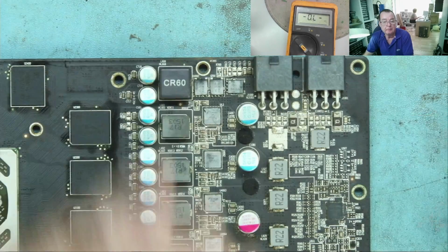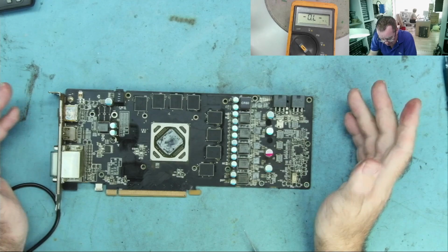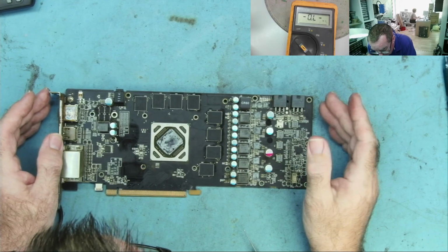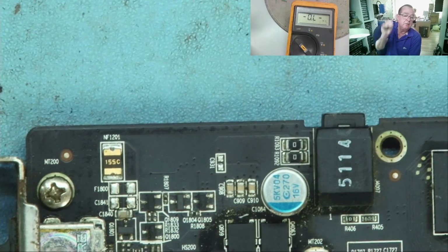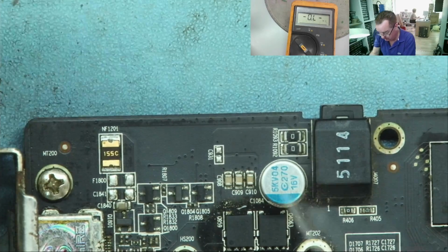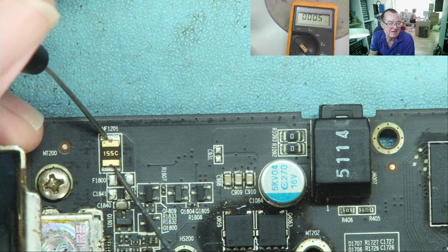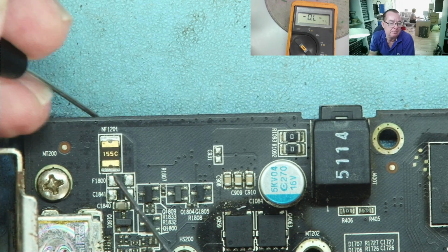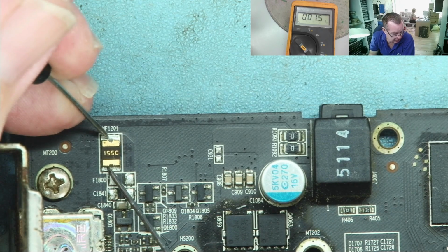Okay. So I hope you can see how we can do these quick checks, and I can do this on any graphics card. I've never seen it before, doesn't matter. There's something else that looks like it might be a fuse there, but it could just be a low value resistor. NF, yeah. Worth checking just to see what this thing is. Reads low resistance. I'd expect it to read low. I don't know exactly what it is, but I'd expect something like that to read a low resistance, which it does. And that's the end of part 2.